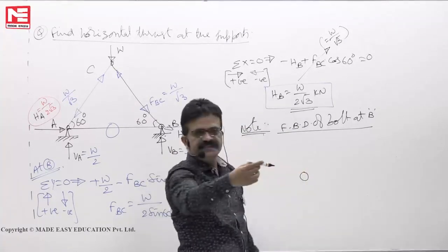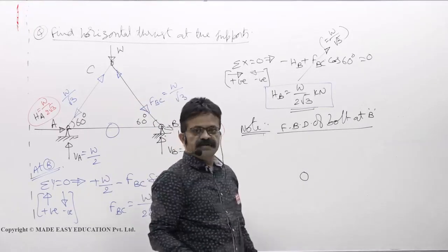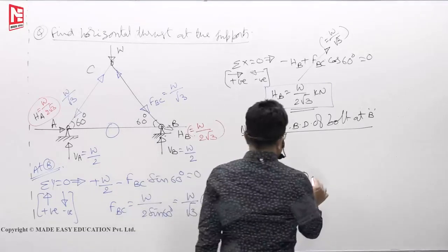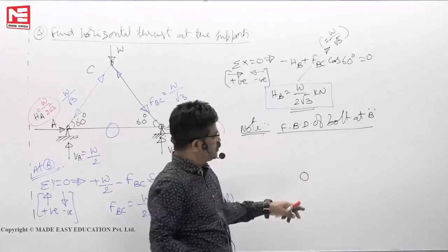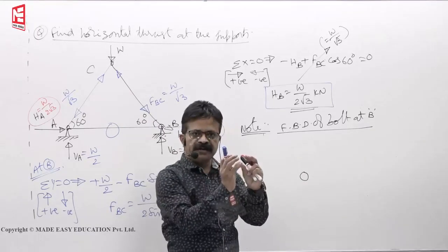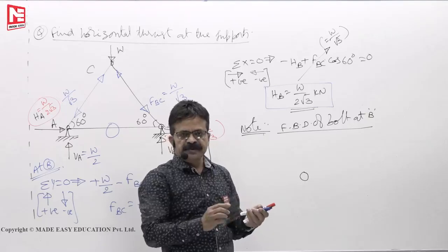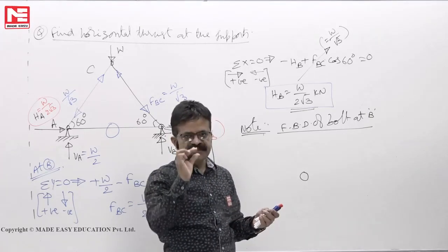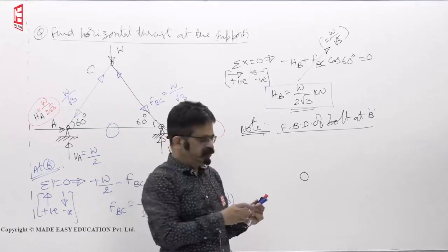Length is sufficiently long to accommodate these two members. Okay. Now this is the bolt at B. A free body diagram is the diagram of a body on which you have to show what others are doing. Who are the others? The pin is resting on the triangular plates. Then what is the triangular plate doing on the pin?